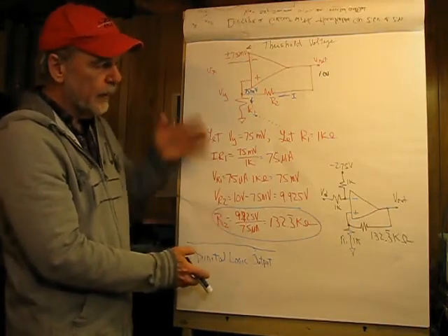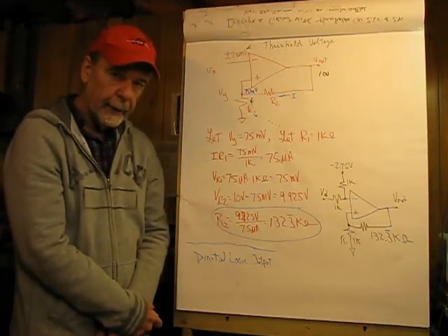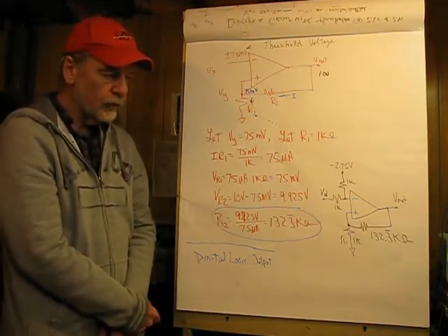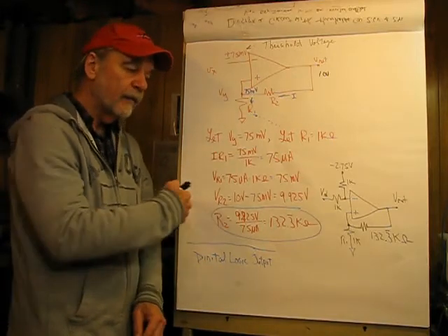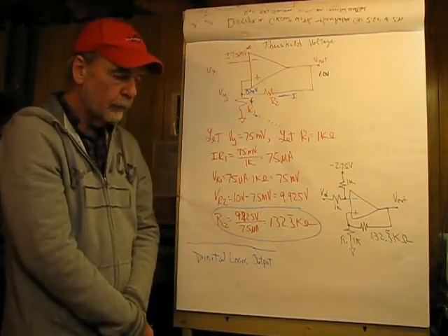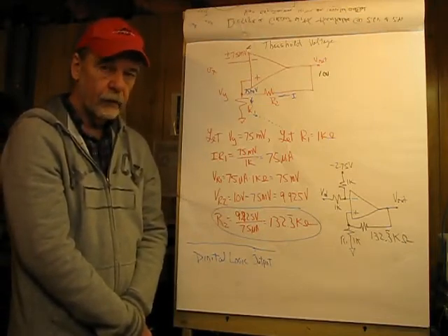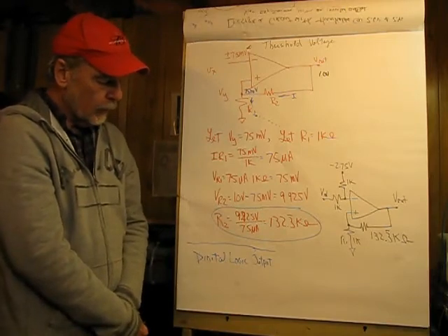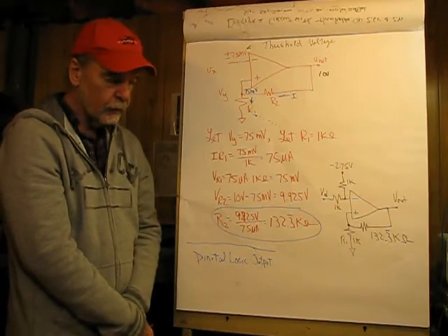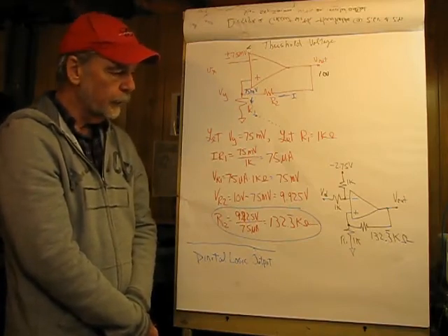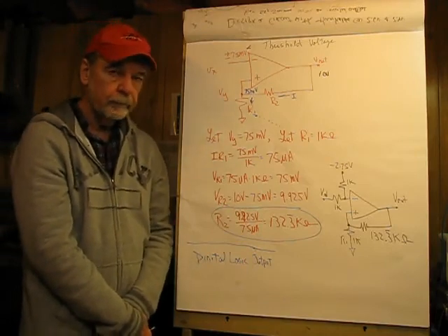The design is exactly what we did here, except we're dealing with a unipolar supply. And then the output will be switching between 0 and some positive value, which to whatever circuitry follows it would be represented by a logic 1, and that's assuming positive logic. So we have a lot of variability here to work with contemporary components, but this is kind of the underpinnings of comparators, and I have to say they can be challenging.